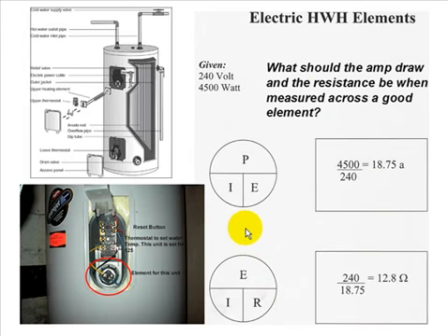What should the resistance be? If I hook up my meter here and it beeps, it makes a noise, or the needle deflects one way or the other, does that tell me that this element has continuity? It can't, because that element is surrounded by water. If the element were wide open, you'd still show continuity on your meter, but you wouldn't show the correct continuity.